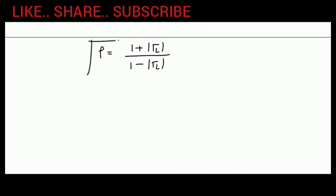Now, there was a question in GATE about the minimum and maximum value of VSWR. We know that for the no reflection case, the reflection coefficient is 0. When the reflection coefficient is 0, the VSWR will be 1.